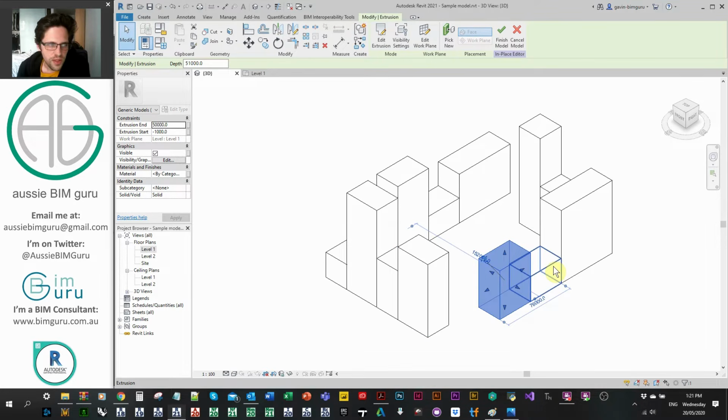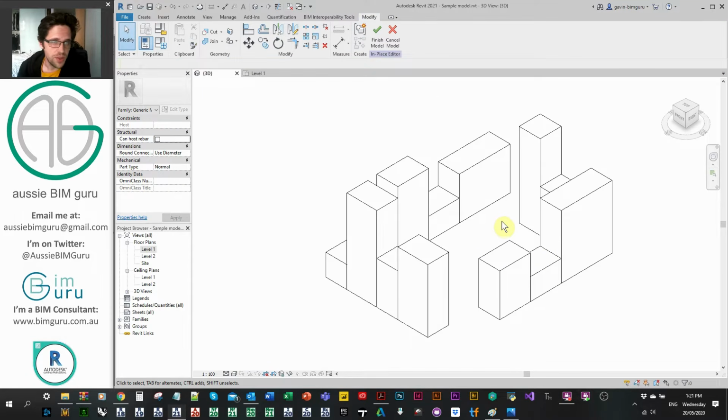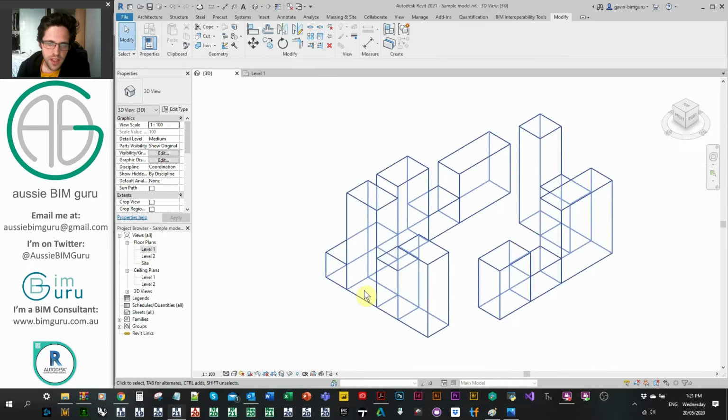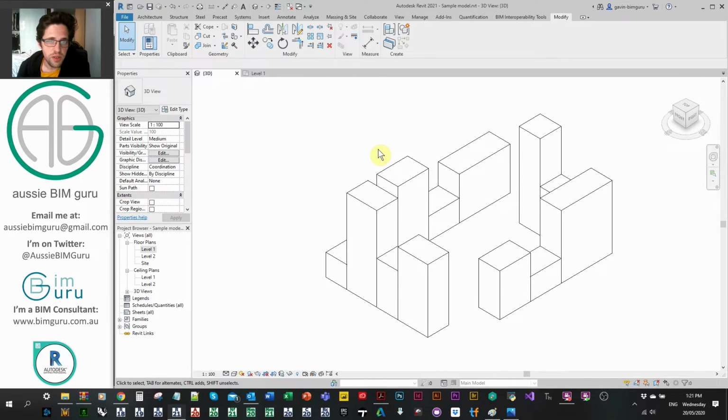There are going to be some issues in Dynamo if you have a really dense, complicated city model, because Dynamo isn't really that good at handling heavy geometry, such as an advanced high-resolution city scan. So in this case, I am using a pretty simple representation of a city, and usually if you were working with a city model in Dynamo, you'd probably have to remodel it or simplify it using a tool like Rhino. But we're just going to work with a simple model.